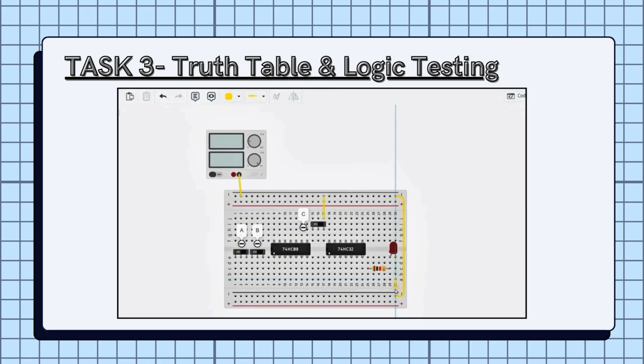The power supply connects to the breadboard to provide power to the ICs. The wiring is set up so that switches A and B are connected to the input of the AND gate. The output from the AND gate is connected to one input of the OR gate. Switch C is connected directly to the other input of the OR gate. The output from the OR gate goes through the resistor to the LED.